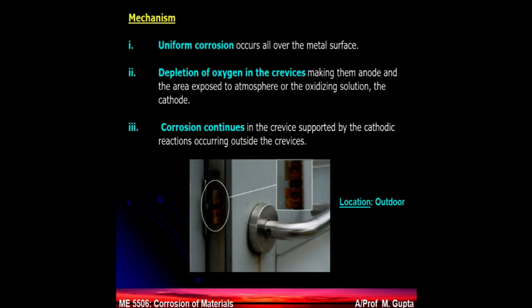It propagates. What will happen if it eats away? Corrosion is the eating away of the material. What happens if you bolt a structure so that it's tight, where the tightness is there because of the threads and everything, and that area is eaten away? It will loosen up with time and it will break apart with time. So that is crevice corrosion.